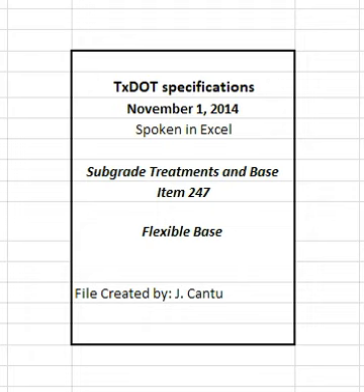When proof rolling is shown on the plans or directed, it will be paid for in accordance with Item 216, Proof rolling. Where subgrade is constructed under this contract, correction of soft spots in the subgrade will be at the contractor's expense. Where subgrade is not constructed under this contract, correction of soft spots in the subgrade will be paid in accordance with pertinent items or Article 4.4, changes in the work.